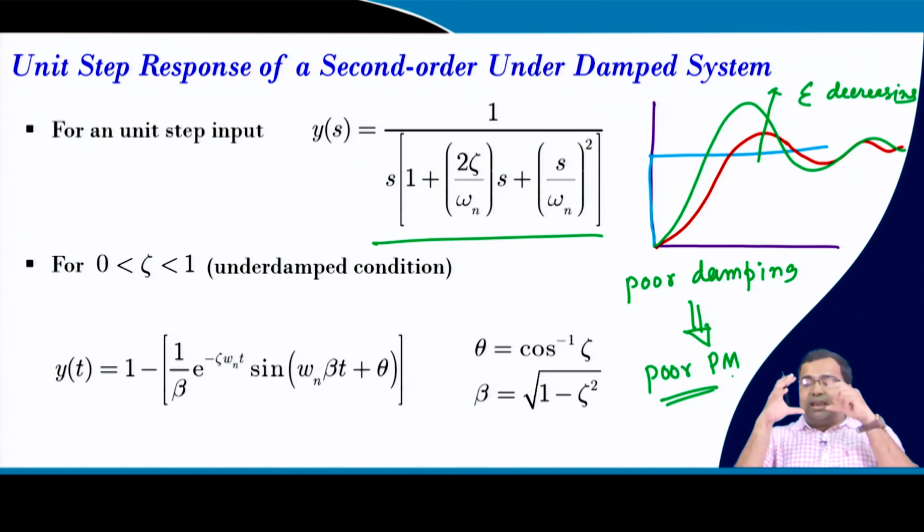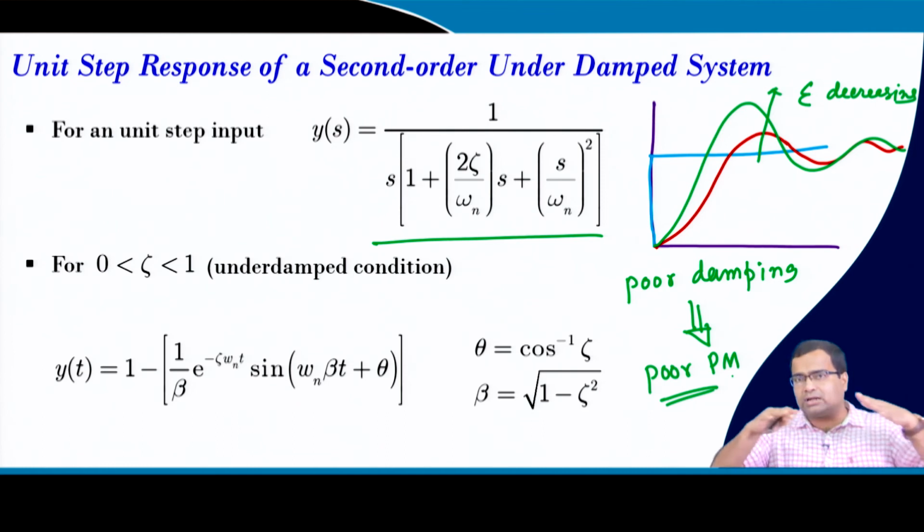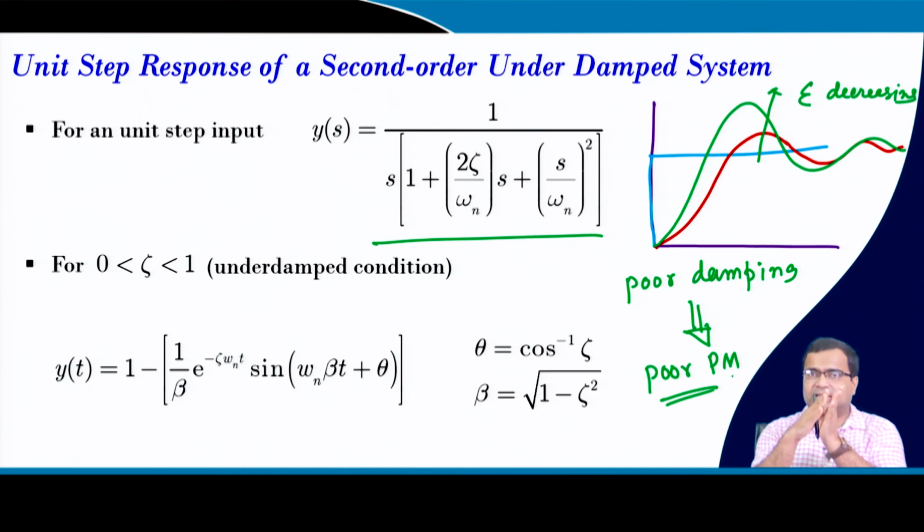That means, if you want to shape the response of the system in closed loop control, we need to provide sufficient phase margin, so that we can cut down the overshoot and undershoot, because those overshoot and undershoot may not be acceptable. And we have discussed in lecture number 13 that the open loop converter has a high overshoot and undershoot, in fact we saw it just in the simulation result, but that is simply not acceptable. So, in case of closed loop, we have to reduce that and keep it within a very stringent limit, because this power supply will be delivering current to the digital processor, where we have to maintain the output voltage of the DC-DC converter within the noise margin of the digital system.